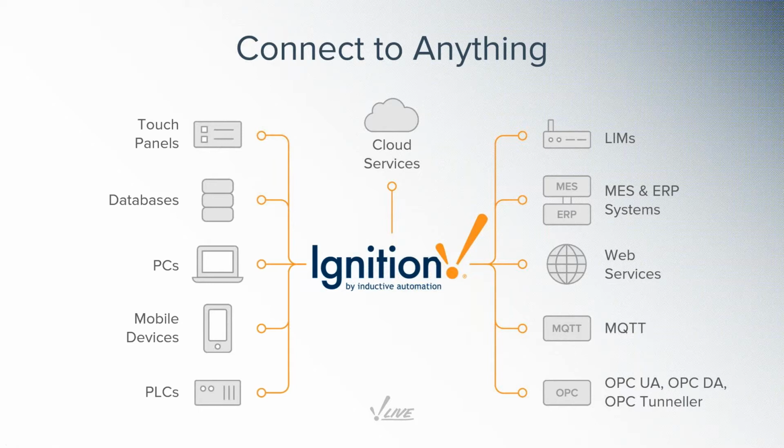We can interface with other business systems. We typically do that through web services, REST or SOAP APIs. That could be other MES or ERP systems, could be maintenance management, could be really anything there. We can bring in LIMS devices, barcode scanners, and scales, and we can parse files and leverage that data. And of course, we can also integrate with the cloud, with cloud services, whether that's in AWS or Azure. A lot of functionality, a lot of places that Ignition can connect to.